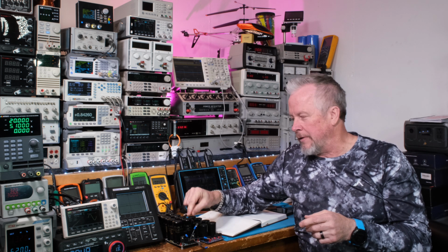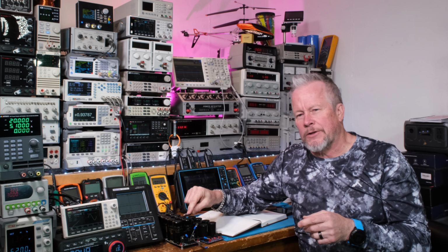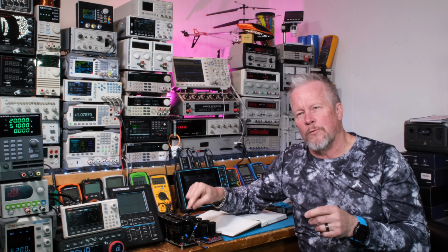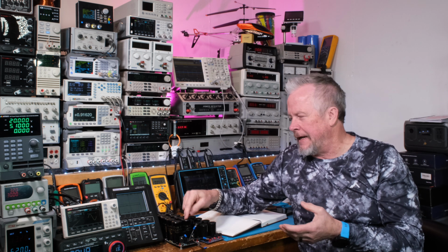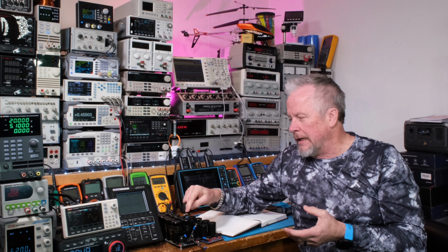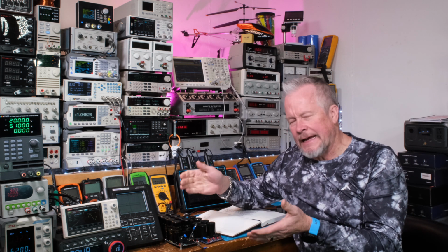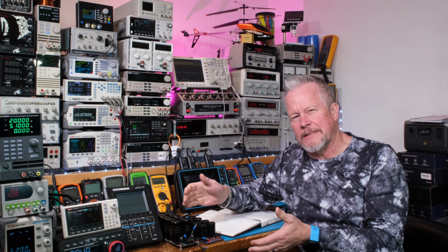Now the other thing is, when I showed you that specification for that capacitor, each capacitor can allow so much ripple current, right? So if you're going to do that 1 volt, and let's say it's 10 amps of ripple, then you want each capacitor to be able to handle at least 10 amps of ripple. So that's an important part of this process: making sure the capacitors can handle that.